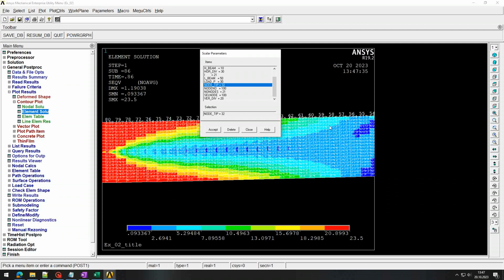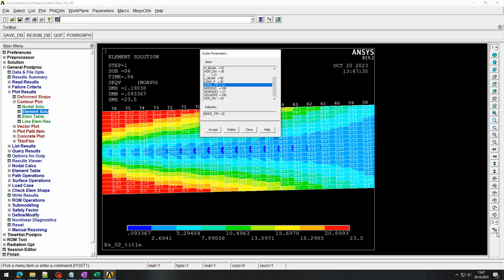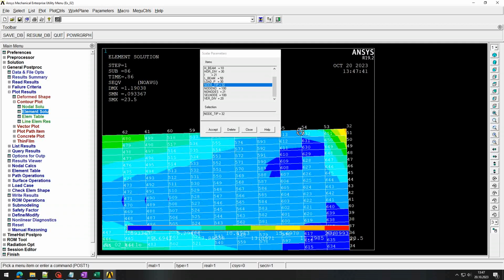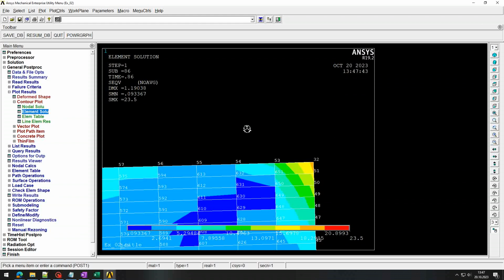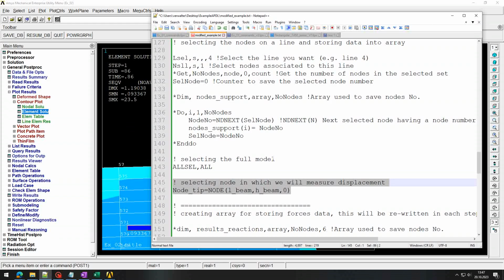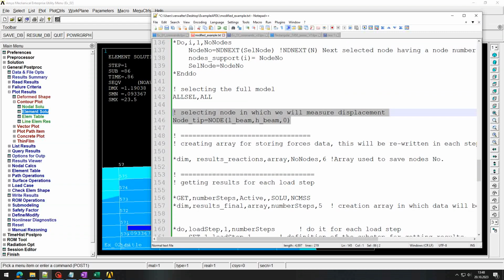If we zoom in to that corner, here is the dynamic model mode in which you can move the model. You will see that exactly that is the node number 32 as written there. Now obviously you can just write down that directly, but if you change the mesh, then the node would change. That is why we have a function for evaluating which is the node associated to that position.